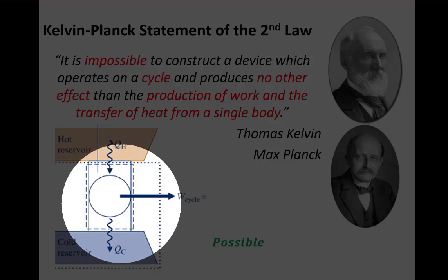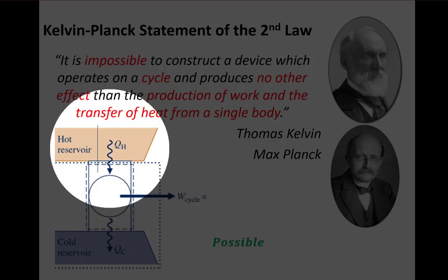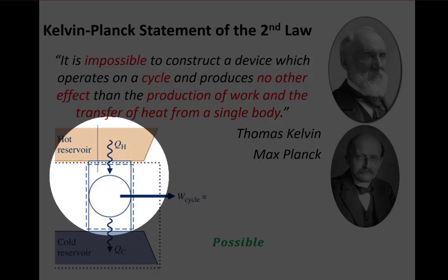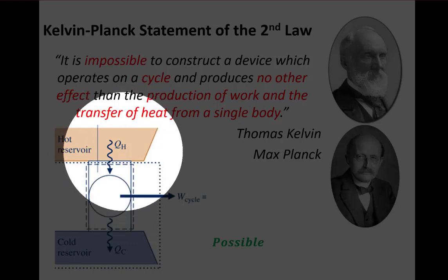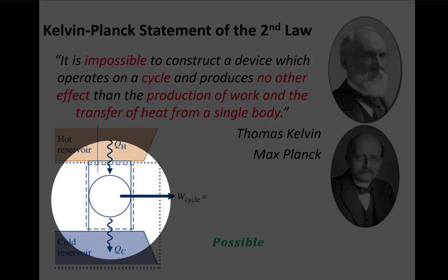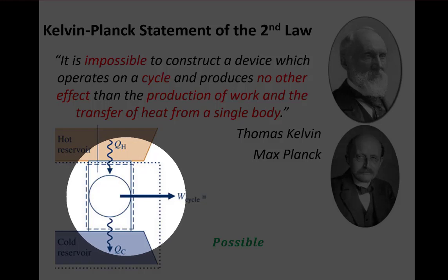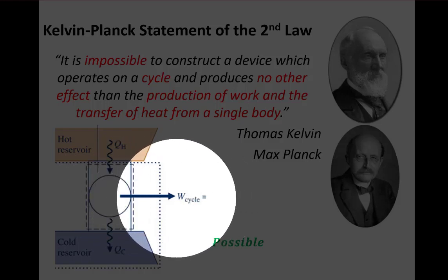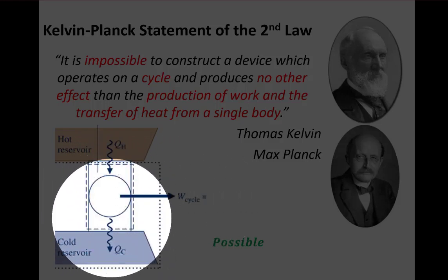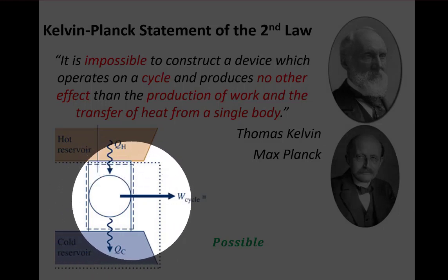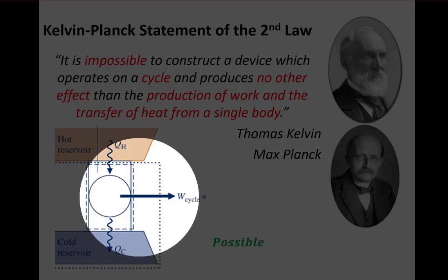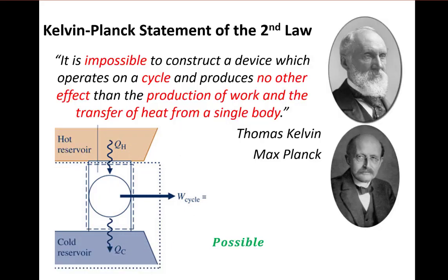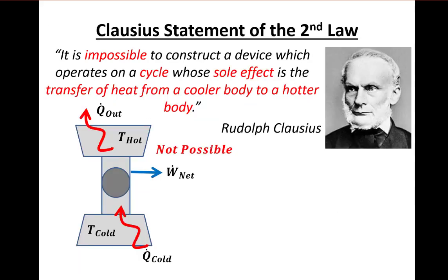And that's a pity because the first law for a closed system tells us that the energy that comes in in terms of heat transfer has to go out, and only the same amount of energy can go out if we're at steady state. So here there's some energy coming out as work, but there's also energy going out by heat transfer. Because we have to cool the engine down, we can never get 100% energy efficient, and probably not even all that close for a mechanical heat engine.